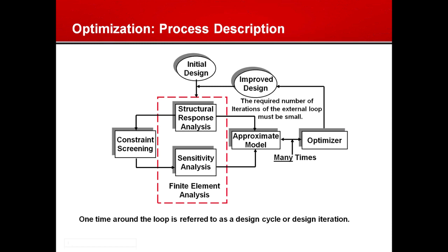Here is a schematic of the design optimization process, and the key strength of the MSC's approach is this approximate model here. The approximate model is basically calculated based on Taylor series approximation and the sensitivities. For each optimization job, sensitivities are automatically calculated.